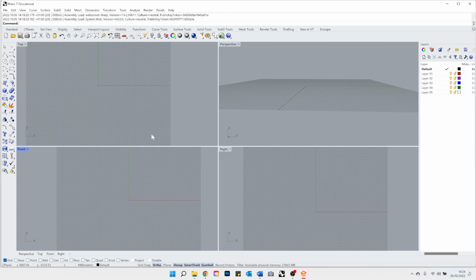And the good thing as well is that if for some reason you don't remember the command, but you remember, oh, it definitely started with O, you can start typing the beginning of its name, and all the commands that start with the same letter will appear. So that's one way to work in Rhino. You also have all your tools, which are on the left here. You have your standard curves, your basic 3D objects, and your modify tools.